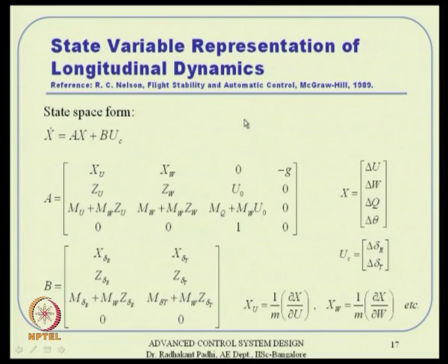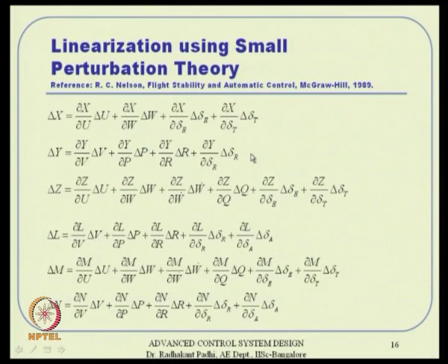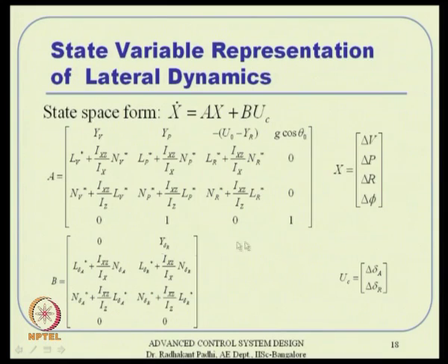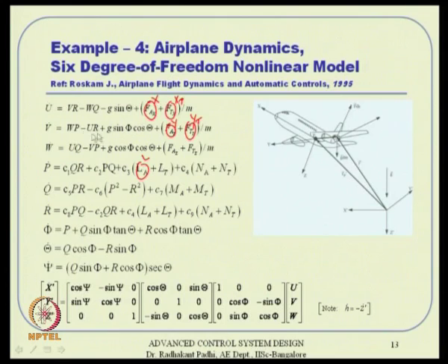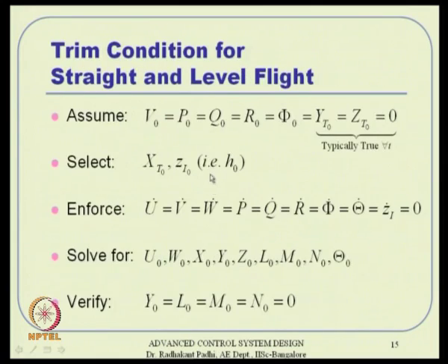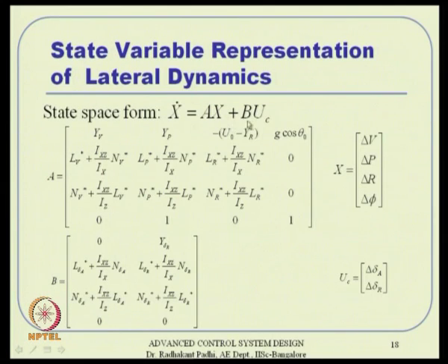But also remember that this x you see here and this u you see here, typically we denote that as u_c, not u, because u is forward velocity by flight dynamics notation, and we do not want to confuse that. u_c stands for control. And then this x and u_c you see here are very different from what you see in this system dynamics. This x means the nonlinear x as it is, and this particular x means this part of the variables.